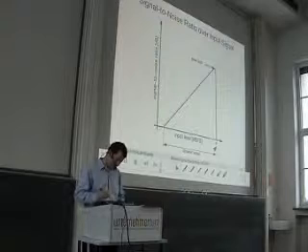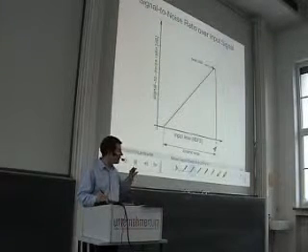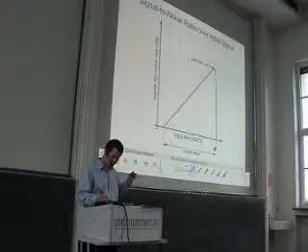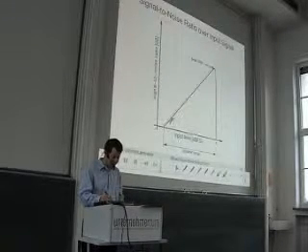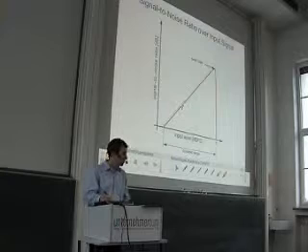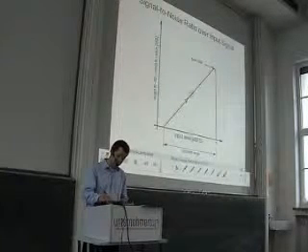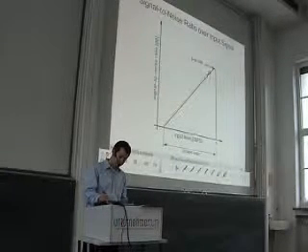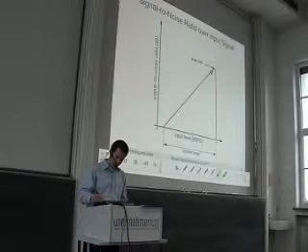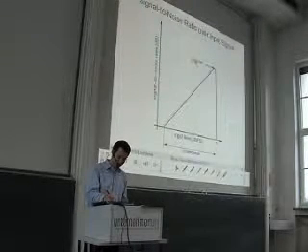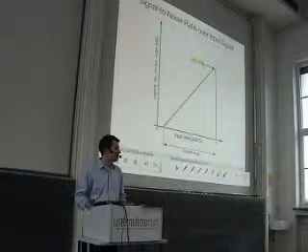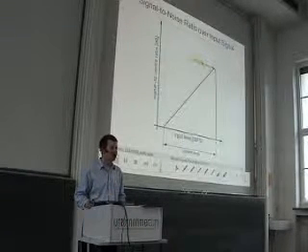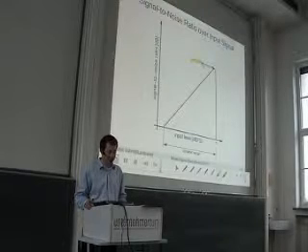So as I said, a very small sine has a small signal power, and if we increase the amplitude of this input sine, then the signal to noise ratio goes up and up and up. At some point it reaches a maximum value, which is the so-called peak SNR, and actually it is this peak SNR that we use for the computation of the effective number of bits.